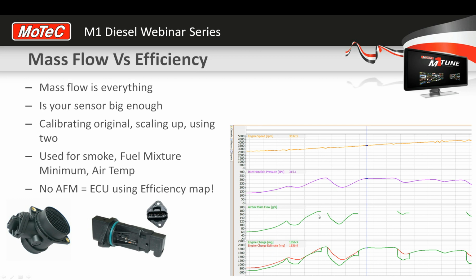So if the air mass flow goes into error, and in this case it's very common to see this, I would suggest that as soon as you start performance tuning a diesel, this is one of the things you look at straight away: make sure that the air box mass flow is giving you a consistent and continuous output reading. So once it gets to the end of the calibration, the sensor goes into error, and we get no more reading from that sensor itself.